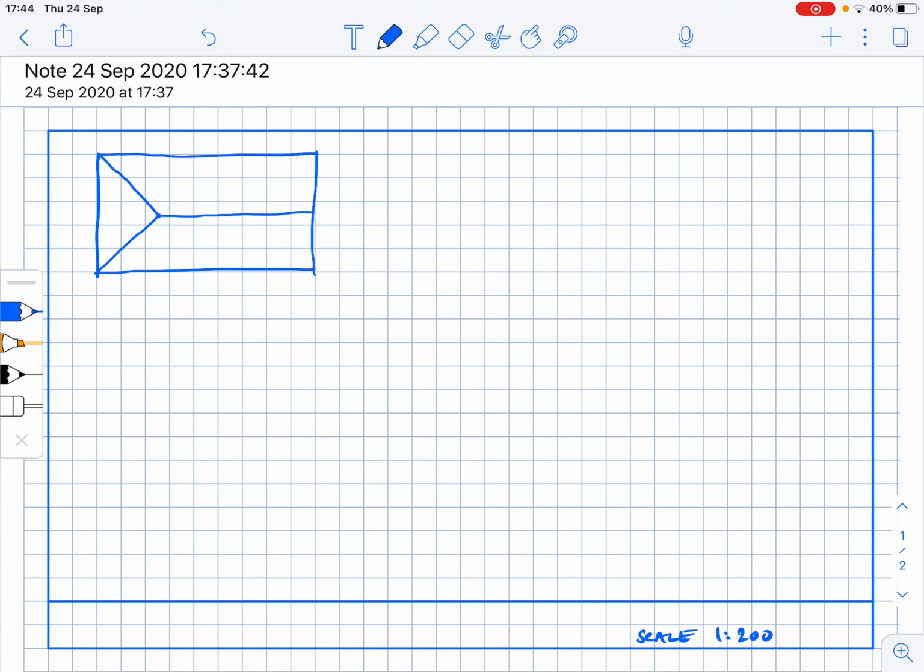You would also put notes on your drawing, and strangely you'd always put "do not scale". So you draw them to scale, but you put "do not scale" because you don't want someone to measure this with a ruler and then build it to that if you've made a little error on the drawing. You really ought to add dimensions rather than relying on people scaling. But drawing it to scale means it looks correct. So that's why we draw it to scale, but put "do not scale".